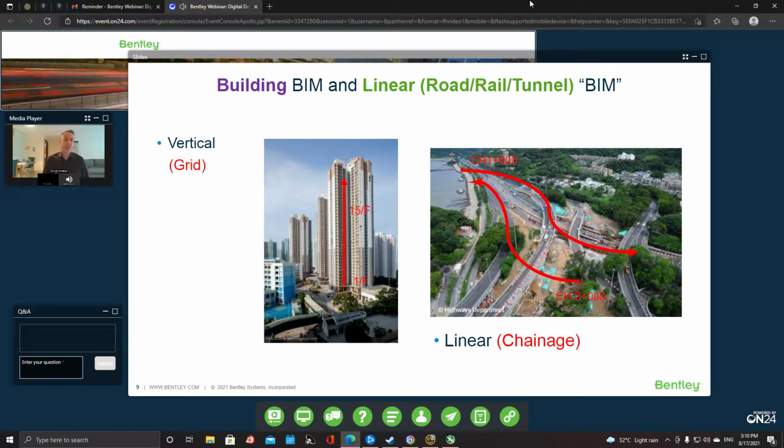And there might also be a debate whether it should be, because IFC is coming from a buildings BIM background. Now, in terms of geometry, what are the fundamental differences here? A BIM for buildings, like Open Building Designer, would be our software for that. Others use Revit, for example. These are based on a grid, and everything sort of stacks up on the grid. When something shifts, the grid shifts, or the wall shifts in relation to the grid. Even if there's a curved wall, it's grid-based.